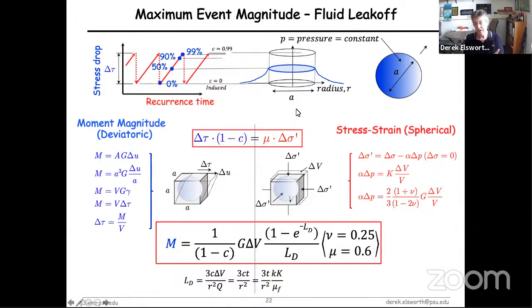In fact, lots of people believe that this lag that you have at the tip of the fracture is the space where the fracture develops before the time for the fluid to be able to infiltrate into that, and you get a gas-filled zone, which is at the vapor pressure of the fluid ahead of the rupture. So that would be kind of the analog, I think, to this unconstrained rupture, the 3/2 scaling versus the constrained rupture. Okay. So I don't know if I answered your question or not.